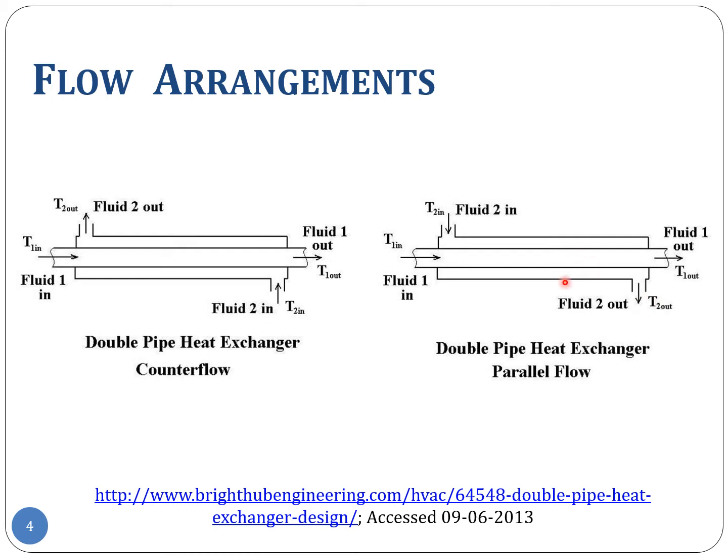So if this were denoted as the z-axis or the axis of flow, both the cold fluid and the hot fluid would flow along the direction of plus z in a parallel flow, whereas in a counter flow, the cold fluid will flow in the direction of plus z, and the hot fluid will be flowing in the direction minus z, right?